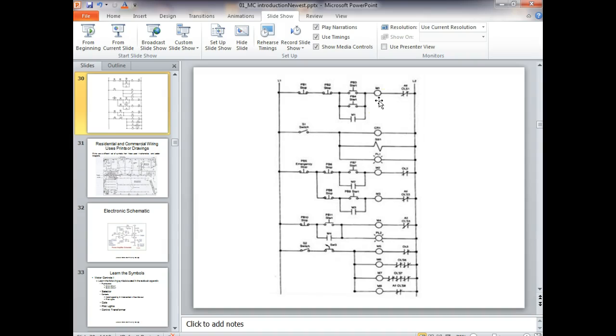Understand? Yeah, this doesn't make it a series circuit. That's a contact. A contact is a control device. It just made it seem like that would be an output. It's not an output. It's a symbol for a contact, and we'll talk about that later on. These are relays. These are coils for relays. These are loads. This is a symbol of what we call a solenoid, and we looked a little bit about solenoids. I did bring my nail in, by the way.